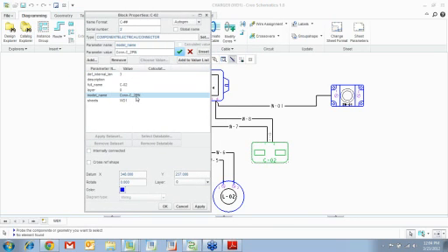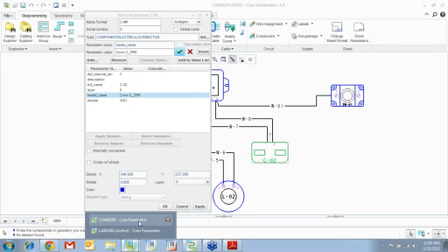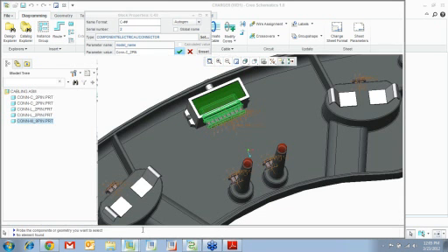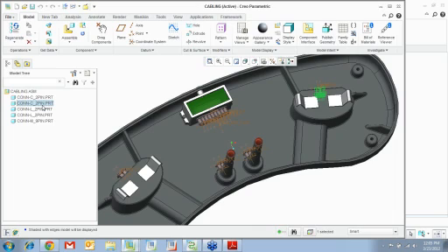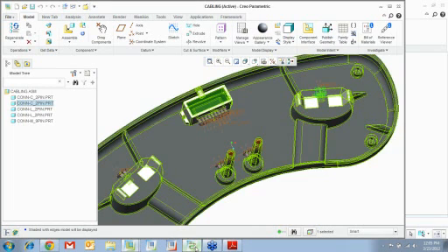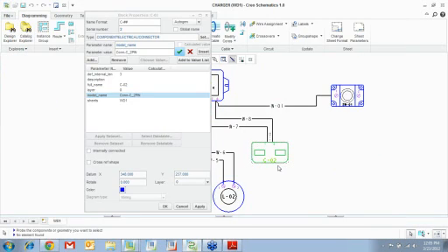Now model underscore name has the name of the ProE part that this is going to map to. So you can see conc underscore 2 pin, which actually is same as conc underscore 2 pin. So that is how I'm going to map this component to this particular block. Okay, that's one important thing.